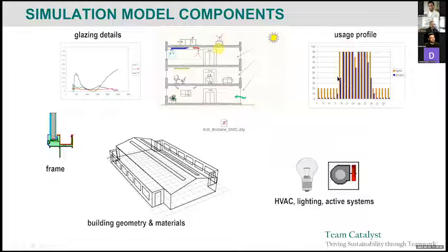A design load for occupancy might be 10 meters squared per person, but across the year, across the days, on weekends and weekdays, you may have different times when you assume people come in, or how many people come in as a percentage of the design. Similarly for lighting systems, any plug loads connected to the building, infiltration rates, and many other things.